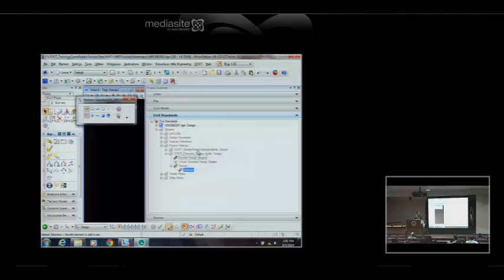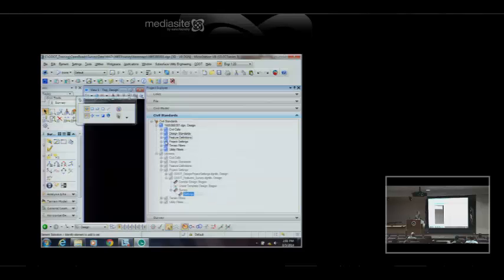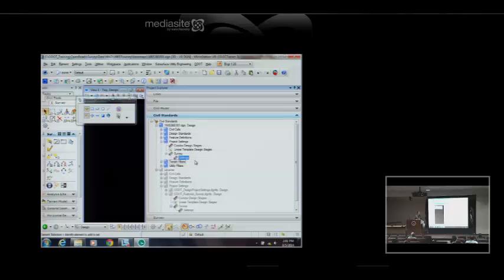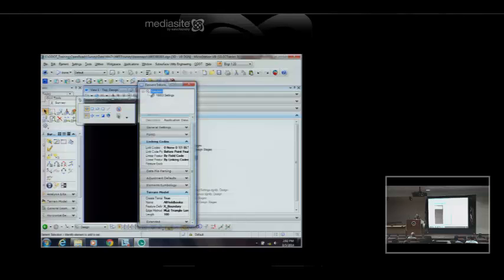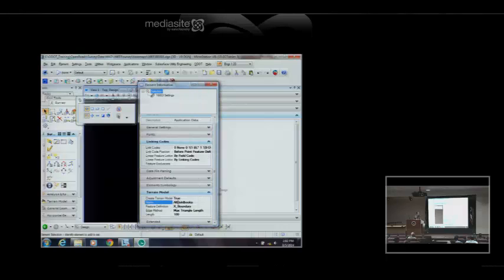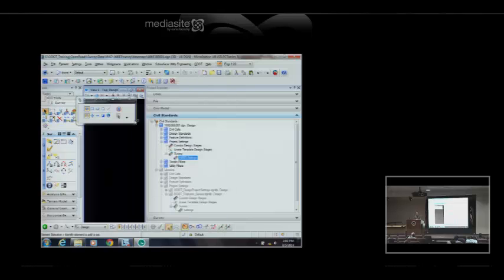So anyway, these settings are read from a DGN library. What I'm going to do is copy these settings into my current file, project settings survey, and paste them in there. I'm going to rename that, and this is PIN number 16653. So I'm just going to call this 16653 settings. And if I look at the properties, under terrain model, there's the default name for terrain models, all field books, create terrain models true. I'm going to make that false. So it will not automatically create a terrain model.